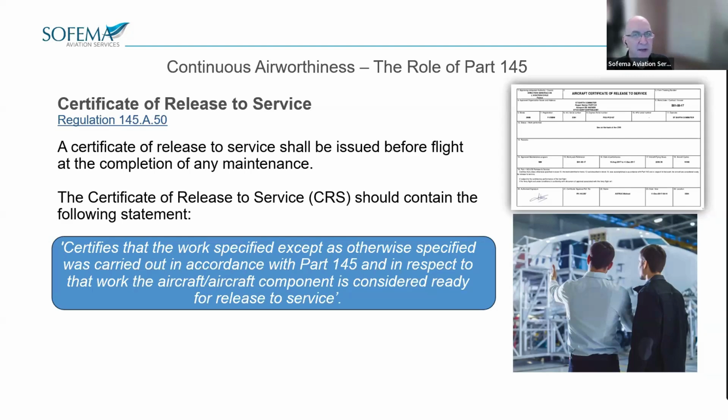Any new defects or incomplete maintenance work orders identified during the above maintenance should be brought to the attention of the aircraft operator for the specific purpose of obtaining agreement to rectify such defects or for completing the missing elements of the maintenance work orders. So sometimes there may be discrepancies found by the operator. Something may not have been carried out according to the original package, and that would need to be rectified.